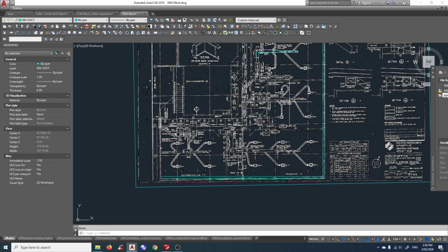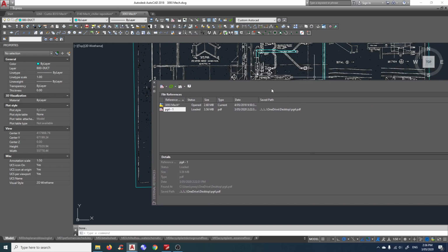Please keep going until you finish. Now there's multiple way to insert PDF into CAD. You can technically drag the PDF into your CAD file instead of doing the file references. What I did find with dragging PDF is sometimes when you change computer, the path is broken, and I have to reinsert and redo all the hard work again, resize, rescale, realign. So that's quite painful. The safest way is to do file reference.